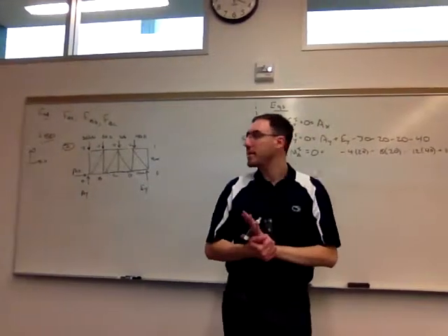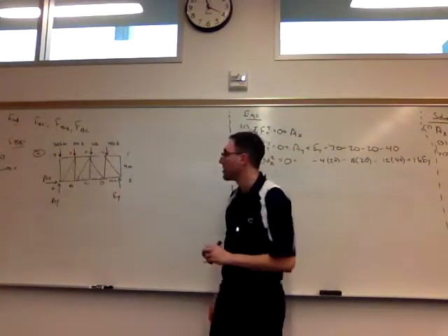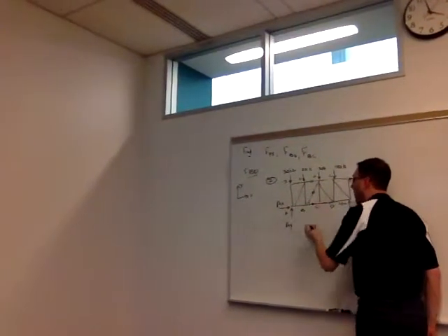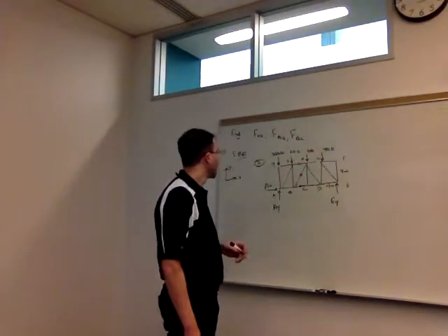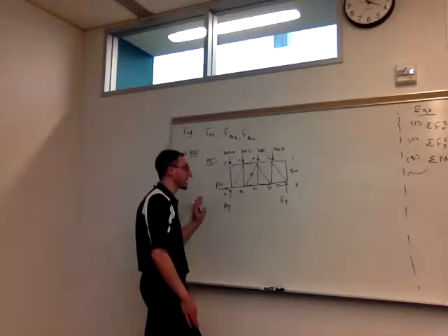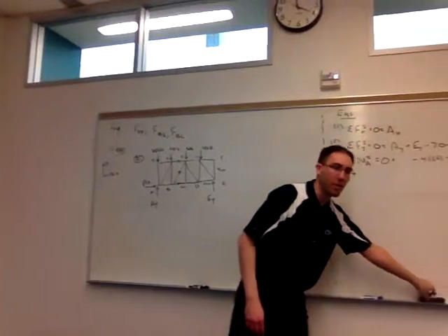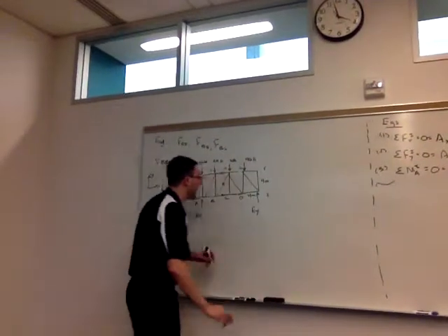But we have to address now what we wanted to find, these 3 internal forces. And in this picture, it can help, especially for more complicated ones, I just want to mark the ones that we're interested in. So this one's pretty straightforward. We want to see, can we make a cut that goes through all of them, or as many as possible, and we'll only go through up to 3 of those members. So we're making a loop that does that.